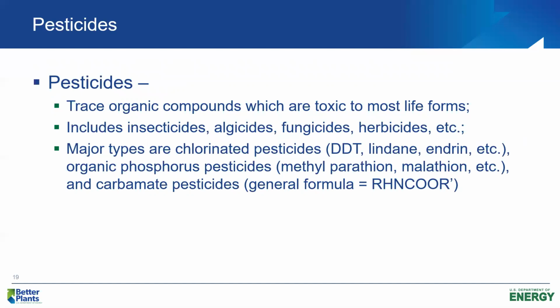Things like lindane, endrin, chlordane, and these constituents created toxicity problems in the treatment plant. And at the intake structure, because some of them were airborne, they actually created toxic conditions in the airspace of the headworks that created health and safety problems for the wastewater treatment plant workers. I believe this is correct.